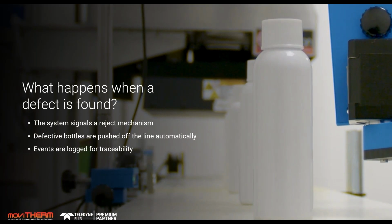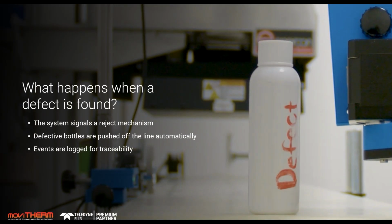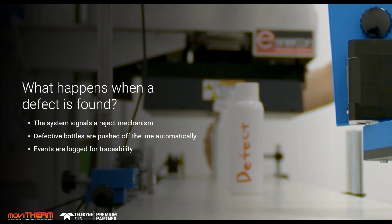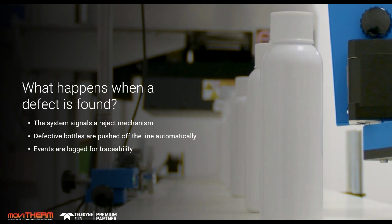In other situations, you may have a PLC that's already on your line that's tracking and doing the reject. And in that case, a lot of the time we can just go Ethernet IP or Modbus TCP and connect our computer to the PLC, and then the PLC will run the logic to kick it out.